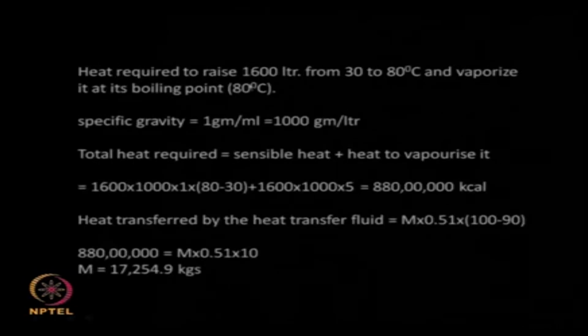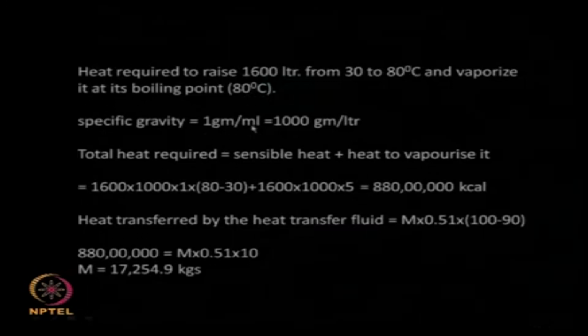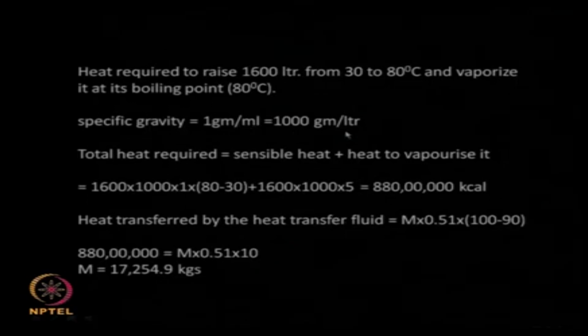Now heat required to raise 1600 liters from 30 to 80 degrees and vaporize it at its boiling point, which is at 80 degrees. Now specific gravity is 1 gram per ml that means it is 1000 grams per liter, correct, because 1000 cc is equal to 1 liter. Now total heat required is made up of two terms, one is called the sensible heat, the other is called the heat to vaporize it.